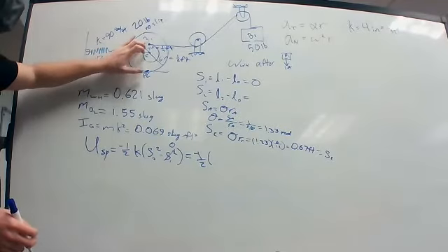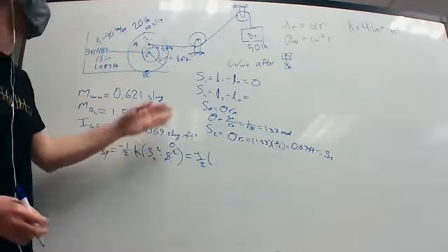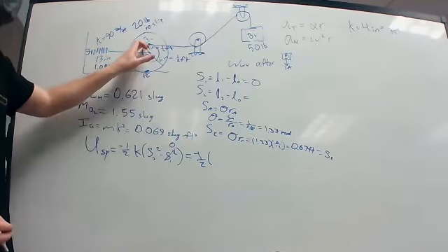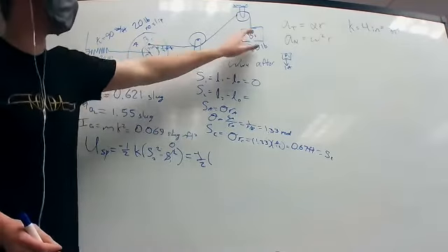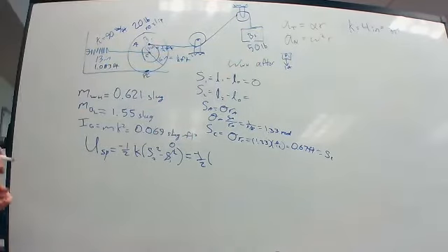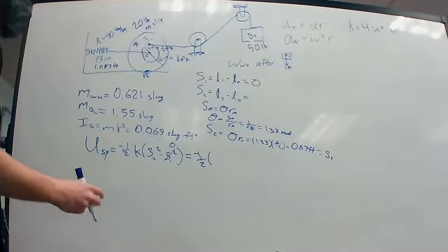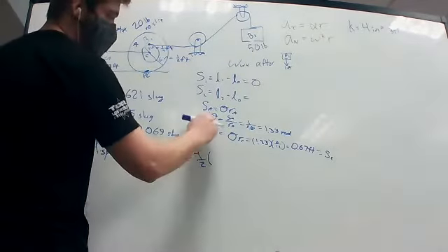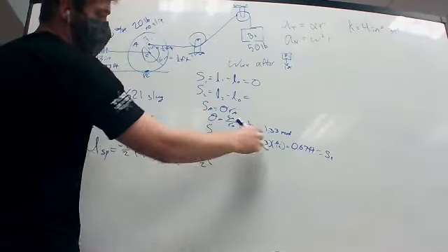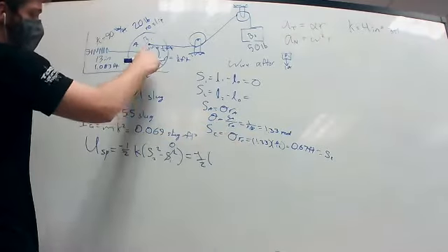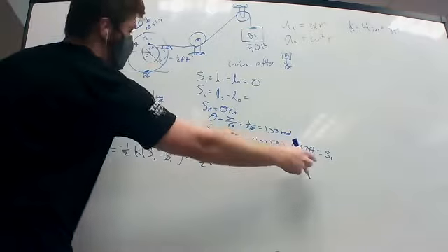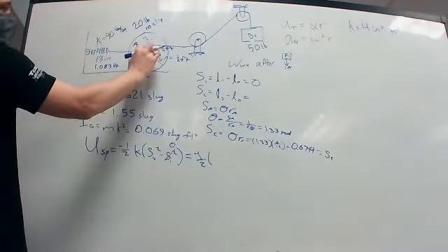So that's going to be 3 and 6, so 9/12. And they say 1 because this distance is going to move 1 foot, just as this distance moves 1 foot. So that's how they solve for SA. And then they use that theta value with RC from the center to solve for SC, which is the same as S2, because that's where our spring is connected.